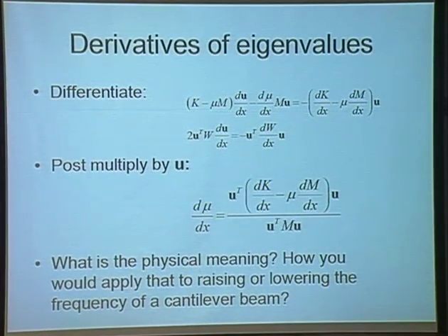That is, U dot is omega U, and so it's the kinetic energy. So if we now want to reduce the frequency of a beam by hanging weights on it, where should we hang the weights? At the tip, right? Because this is the place where we will impart the maximum.